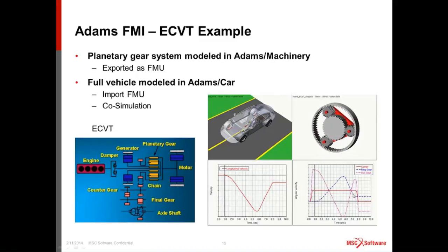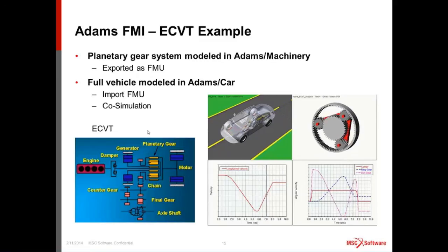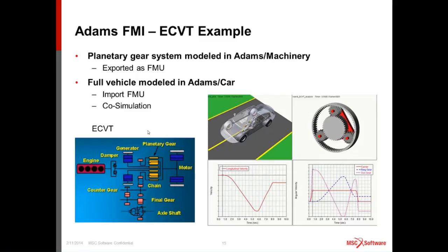And in the end, there's a short period where the engine, which is connected to the carrier gear, as you can see here, is shut off, and there's a short period of pure electrical drive of the vehicle. And this is actually the first time that two Adams sessions could co-simulate with each other. Previously, without this FMI interface, it would be very hard or impossible to do.